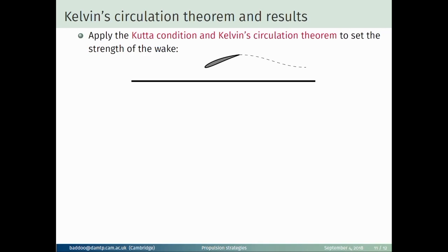And the last bit to do is to apply the Kutta condition and set the intensity of the wake, which we do using Kelvin's circulation theorem.